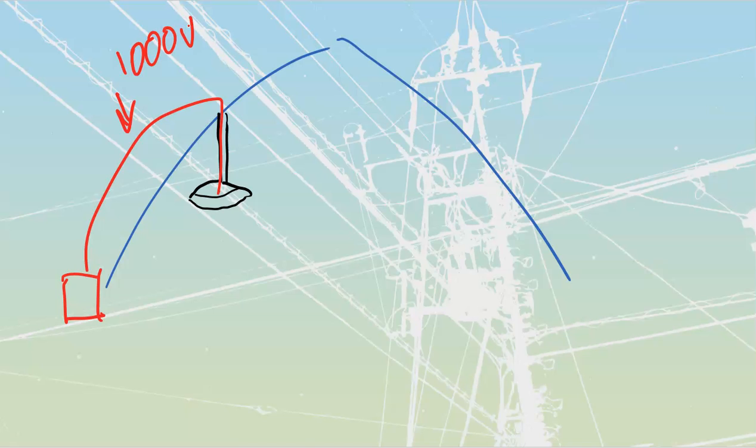Controls for HID fixtures. This is going to be something that, once again, is a little premature for the fluorescent, but we'll cover it because we're in here right now. HID fixtures are going to be our ballasted lights, and if you've ever worked around those big ballasted metal halide or anything, you know that if you shut them off, they take a long time to restrike. Because they take a long time to restrike, we need to have some other method to ensure that there's light if and when we need it.